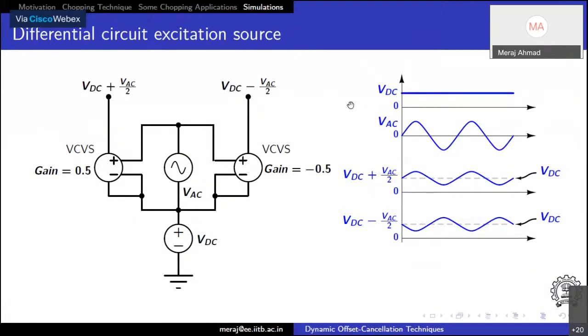Now, for simulating a differential circuit and a single-ended circuit. In CMOS, mostly we use single-ended circuits, meaning we have only ground and VDD. We will not have minus VSS. So all the inputs to our amplifier and choppers need to be shifted a bit, anything in between the supply rails, and the sine waves can be given like this. We can make this in Cadence simply by using a voltage controlled voltage source. There is a reason behind using this type of topology.